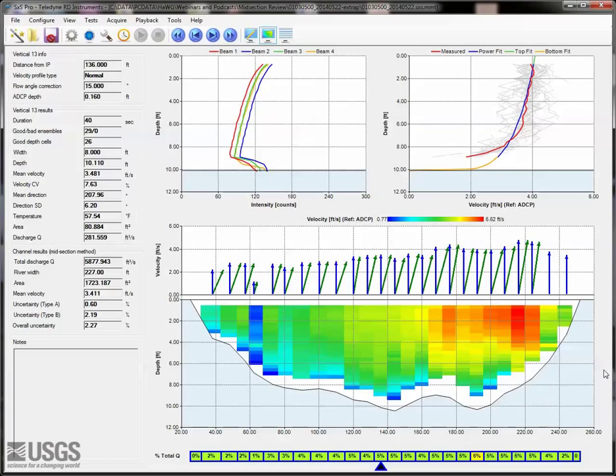After your evaluation is complete and you've selected the method that you feel is appropriate, there are a couple steps left. First, check the change in final discharge from the default power to the method you've selected. If the change is very minimal, say less than 1%, it is typically not worth additional consideration. If the change is quite large and uncertain, you might need additional examination, and downrating your measurement based on the amount of estimated uncertainty from the extrapolation method would be appropriate. Also, if applying a change, make sure that change is documented in the field notes.